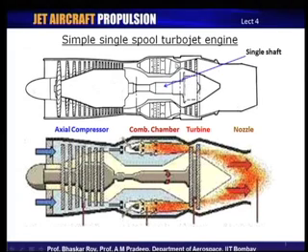Now, again you will see there is a small duct over here, which is the releasing duct from the combustion chamber to the turbine, and once it is released to the turbine, it essentially extracts work out of this high energy gas, which has high pressure and high temperature, both in the form of essentially potential energy. So, this potential energy is then extracted in the form of mechanical work, which this turbine essentially uses to run the compressor through the shaft.